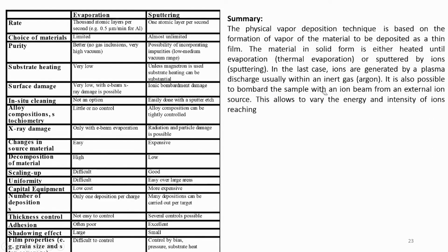When we compare e-beam and sputtering, if you compare the rate, choice of material, purity, substrate heating and several other parameters, you will find that sputtering is way better in a lot of applications and a lot of parameters compared to evaporation. However, depending on the application, a researcher will select a type of technology.